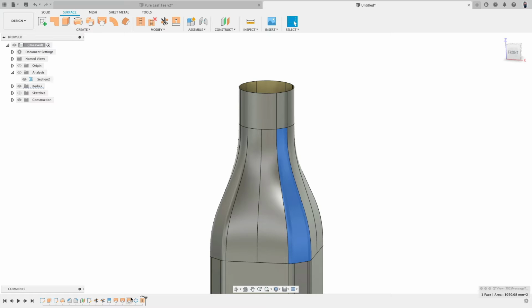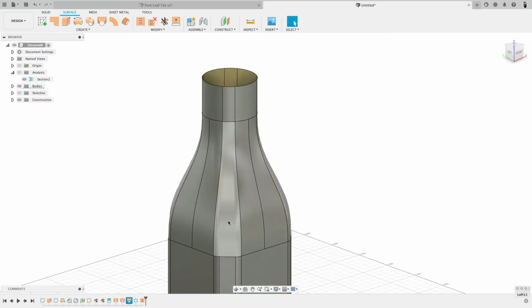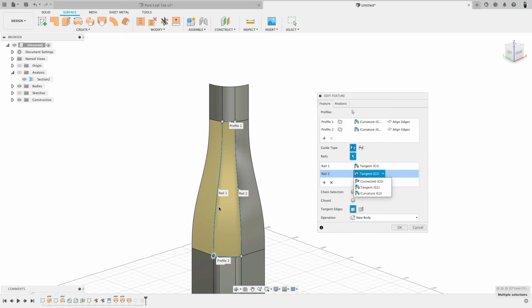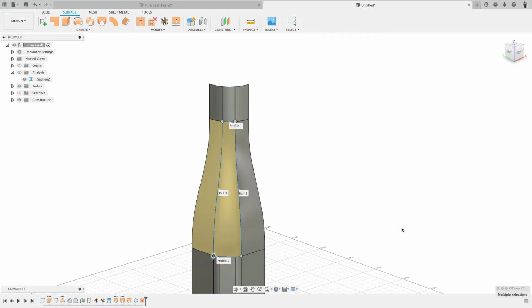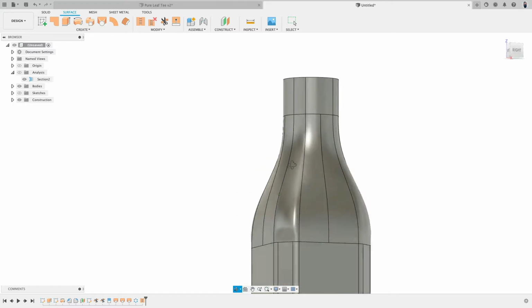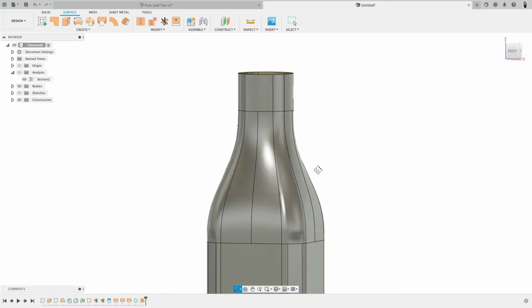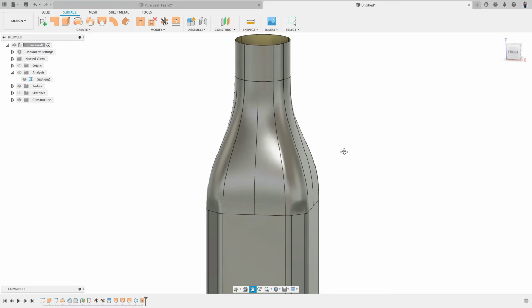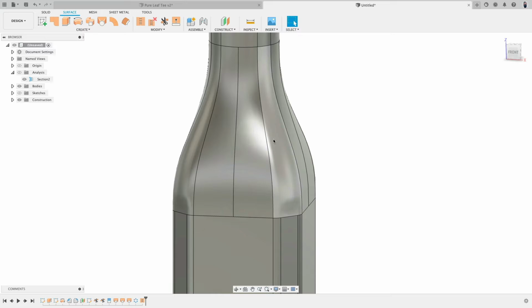Okay, so this is my loft. Where is that loft? Is it that one? So double click. Yep, it is. So this one here, which goes to here and to there. Let's go G2 and G2. Okay. Oh, what's going on here? So for a beginner, this might be very difficult to understand what's happening. But now we tell the surface to here and the surface to there flow into G2. So super smooth. And G2, think about, needs a longer distance to blend.